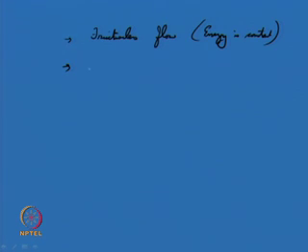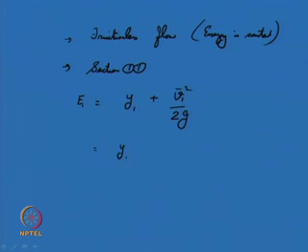At section 1, you have your specific energy E 1. E 1 is equal to y 1 plus V 1 squared by 2 g according to our formulations. This is nothing but y 1 plus q squared by 2 g B 1 squared y 1 squared.